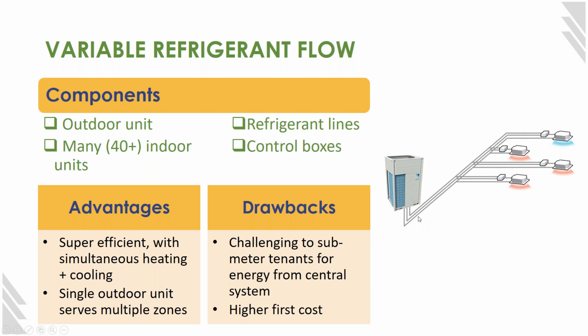If you think about the number of outdoor units you would need to have an individual mini split outdoor unit for every apartment, you'd have 60 of them. And instead they had 5 of these. And these are about the size of a luxury refrigerator, like a proper mansion refrigerator, but a refrigerator nonetheless. They're not gargantuan. And I was just amazed at how much roof space they had. So that's a major advantage of these: you have a lot less space taken up outside.